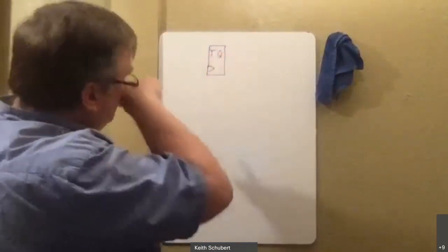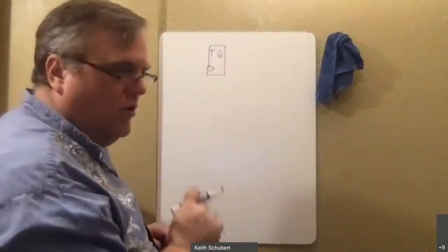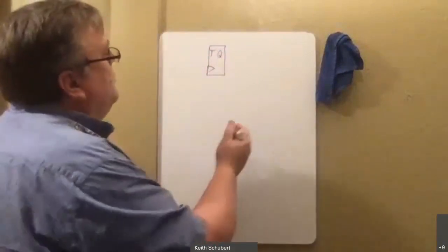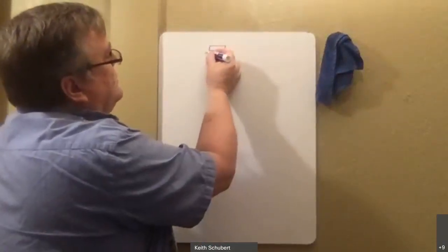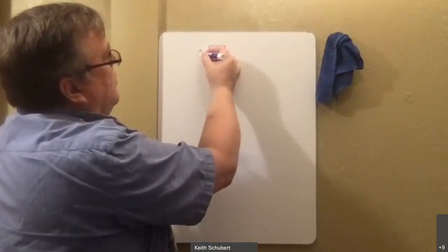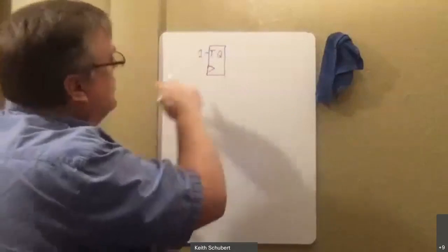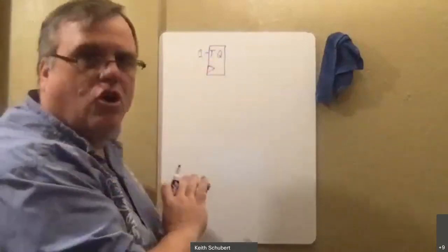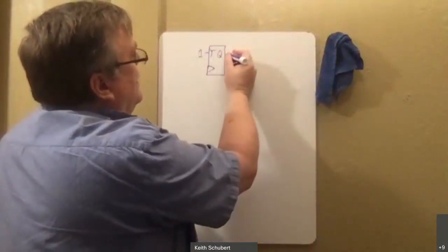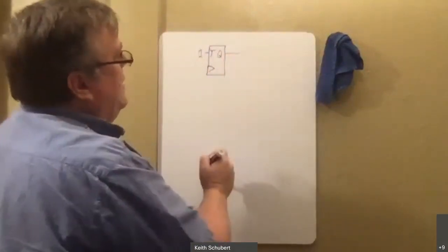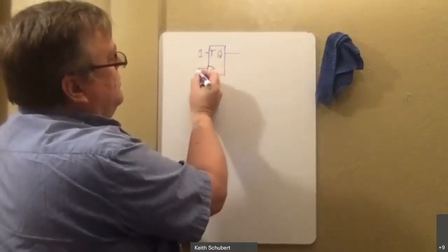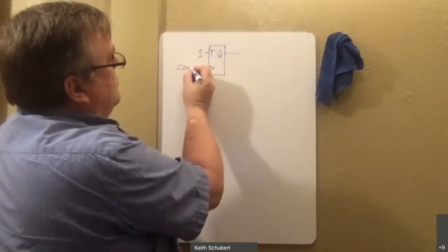So I'm going to start off with what's used for the ripple counters, which, like I said, I'm not a huge fan of, but it is a standard design and it's helpful to understand what's going on with them. So imagine I set this toggle to 1 so that it's just always going to toggle if it gets a clock impulse. And then my Q is going to be my count. And then on here, for the clock input, I put my count signal.